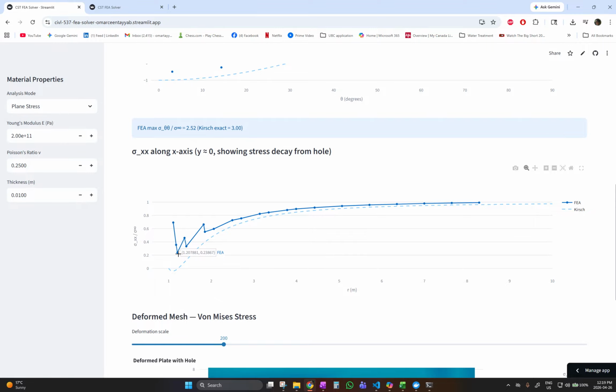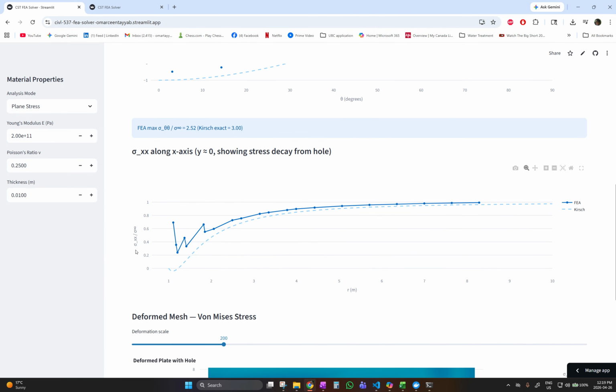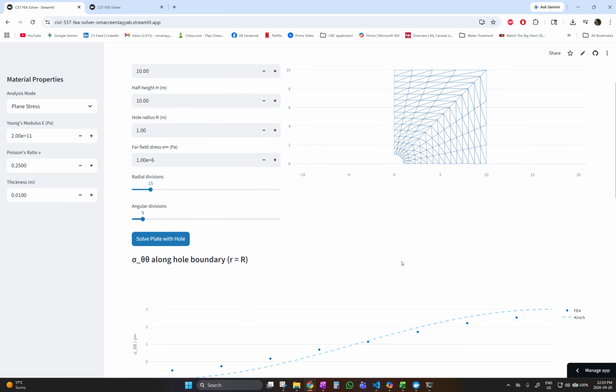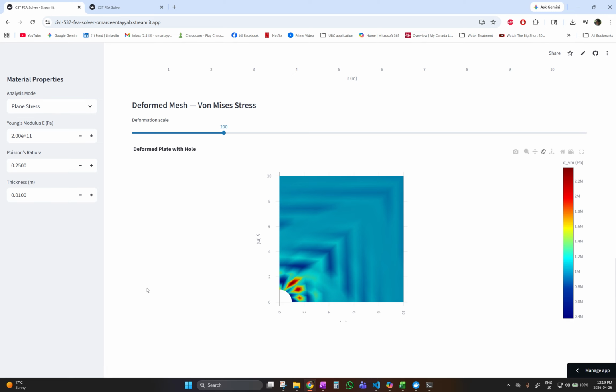As we move away from it, we have more and more material to build stress onto, until we finally get here and get a value of one, and that has to do with the traction free boundary condition. Basically, the hole has no material, and there's no loading inside. That's my explanation. And you can see, with an unrefined mesh, it's not near the equator. It's actually 67.5 degrees.